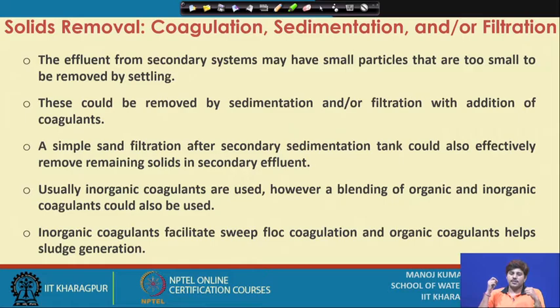Still there are some solids, particularly the fine sediments, that do not settle in either the primary or secondary sedimentation basin because of their smaller sizes. Particularly in the secondary, there is a little gas production as well, so many times these solids are attached to gas molecules, which makes them lighter and they do not settle. This could include even some of the bacteria which are not removed in the secondary sedimentation, and that also comes in the effluent of the conventional wastewater treatment systems.